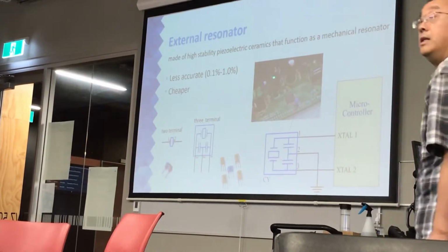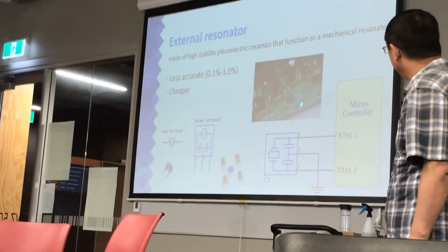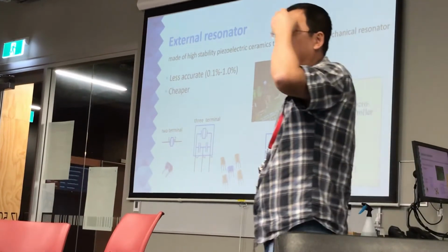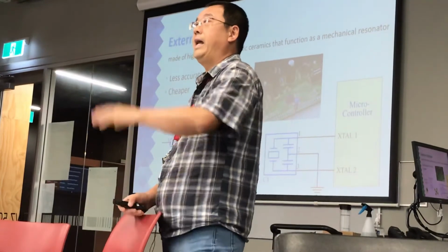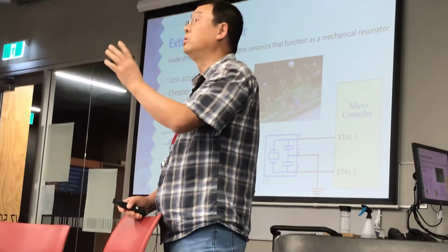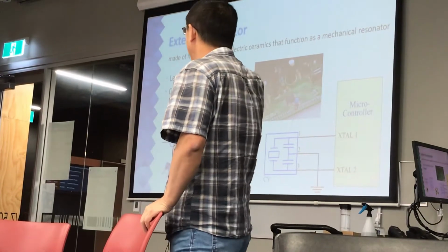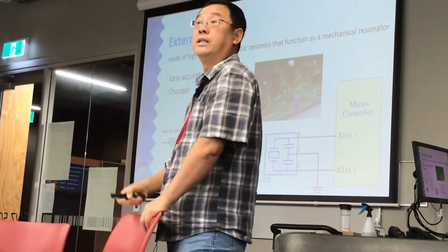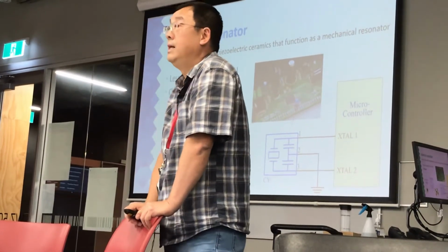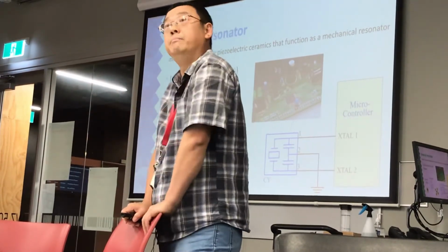Look at this microcontroller PCB. You can see that's the microcontroller, and that is the external resonator. When you lay out the PCB, you've got to be careful. Anything that deals with a clock is going to create noise, because the clock is turning on, charging, discharging. They produce pulses, and the pulse can go 8 megahertz. If you select a 16 megahertz microcontroller clock, then the clock can go 16 megahertz, and some can go 20 megahertz.